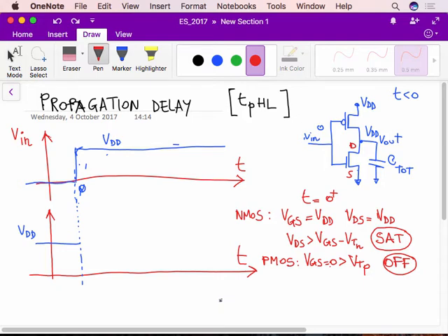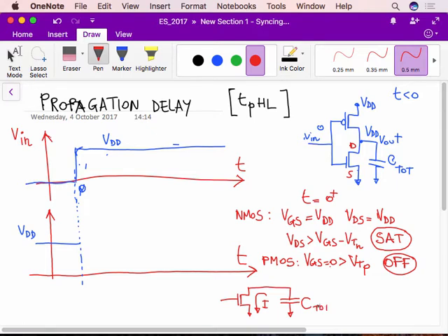It has become essentially a circuit in which you only have the NMOS, which is conducting, so there is some current in the NMOS, and this NMOS is driving the voltage of the output capacitance down because this current is discharging the C load. Okay? So basically this current is removing charge from the capacitance and therefore is pushing down the output voltage, which is the voltage on the capacitor.